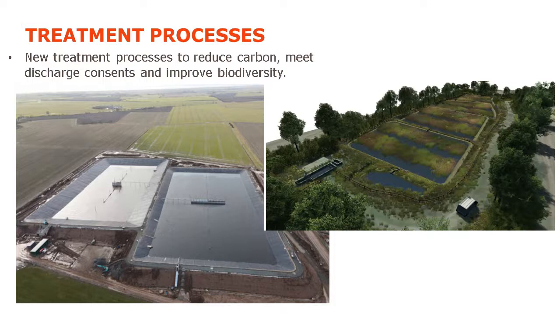In many sites, we've already got the existing wastewater treatment works, and we're trying to make those assets work harder. So we may put additional assets between existing assets to try and polish the effluent to remove that extra phosphorus.